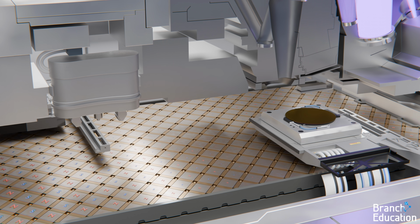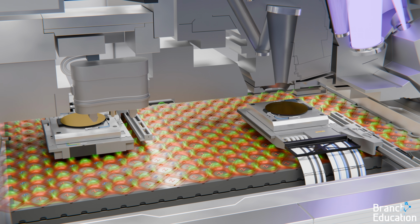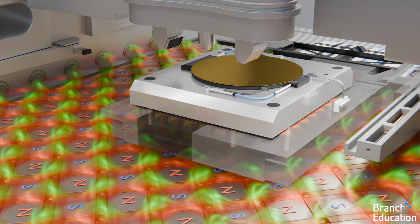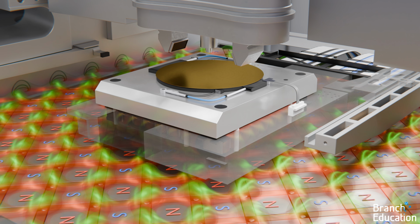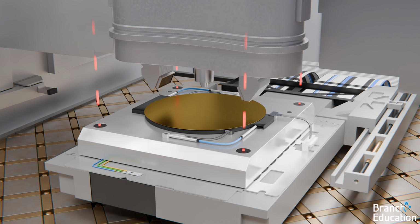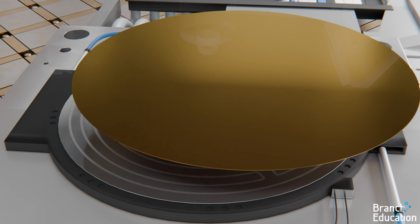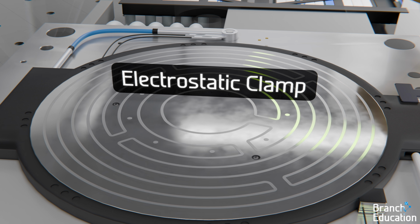Specifically, the wafer stages levitate on a large magnetic table composed of more than 1,000 magnets. Electromagnets on the underside of the wafer stage move it along this magnetic table both quickly and with micrometer-level accuracy, while interferometers on the top of the stage measure its exact position, and this setup is called the long stroke stage. In order to secure the wafer, it's placed on a plate, which is technically called an electrostatic clamp.